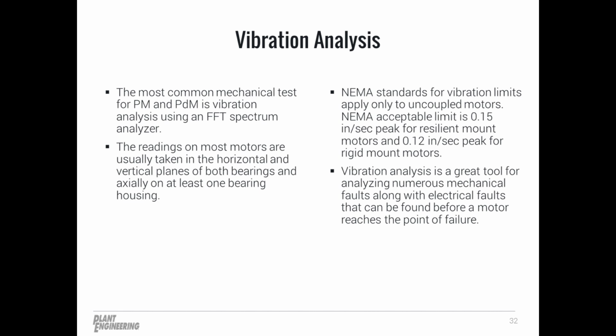There are standards that apply to the acceptable limits of vibration, but you may note that the standards such as NEMA state the acceptable limits apply only to uncoupled motors, where most of the time we're starting our analysis with the motor coupled to the driven machine.